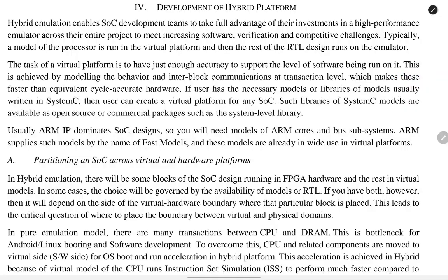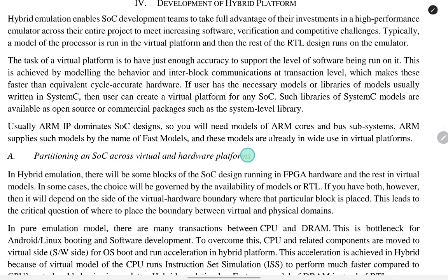This is achieved by modeling the behavior and inter-block communication at the transaction level, which makes these models faster than equivalent cycle-accurate hardware. If a user has the necessary models or libraries of models, usually written in SystemC, then the user can create a virtual platform for any SoC. Such libraries of SystemC models are available as open source or commercial packages, such as a system-level library.